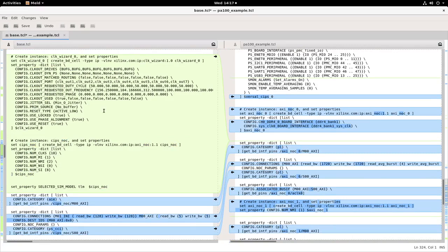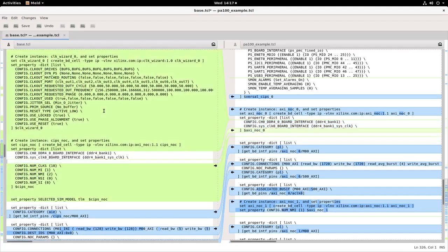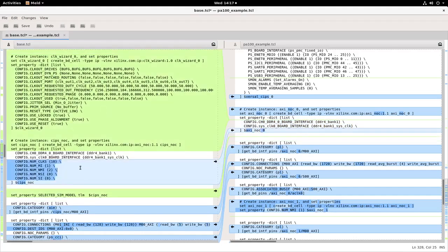It doesn't matter in principle which one we choose to add the memory controllers, because they are both DDR memory controllers. The only thing to take into account here is that AMD's example design has LPDDR memory, whereas the PA100 has 2 banks of DDR4 memory.